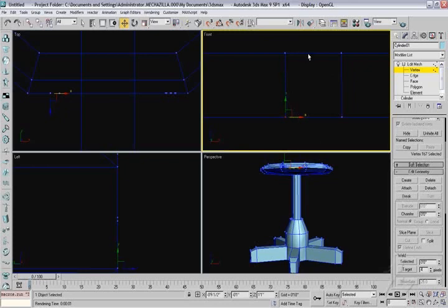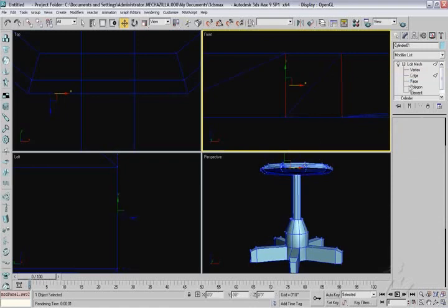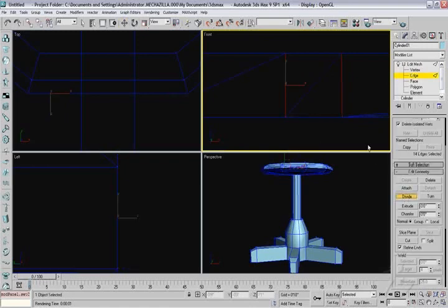And then of course I'm going to divide my edges now. So we go back to edge mode, use our divide tool, and then the two red lines we definitely want to divide, and then also the bottom ones that make up this short little square. And if you have to, jump back to vertex mode. As you can see here, I clicked off the line, so I just created a new vertex out in the middle of nowhere. So I gotta undo that by using Control Z, and then go back to edge mode, and I'll divide that edge one more time. Don't forget your undos, that helps.